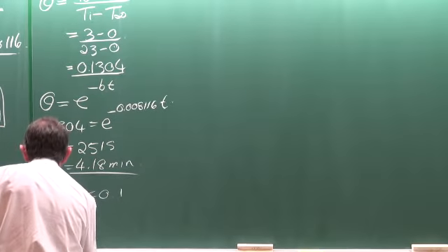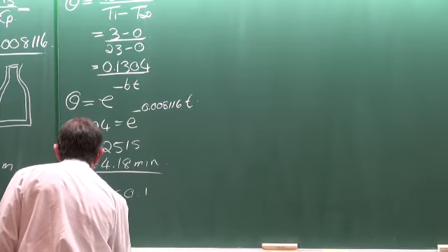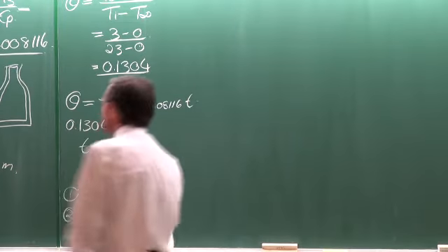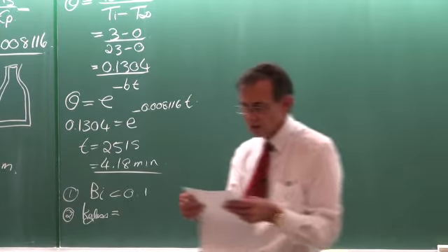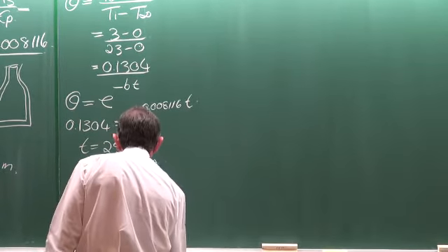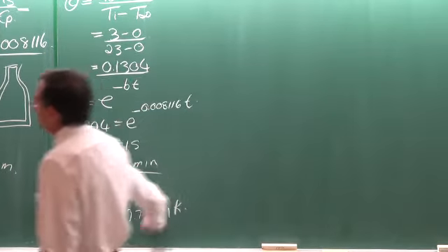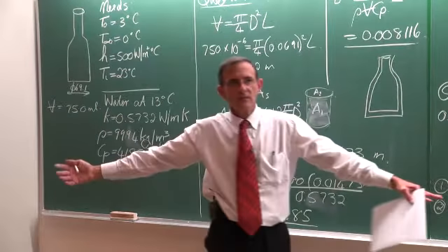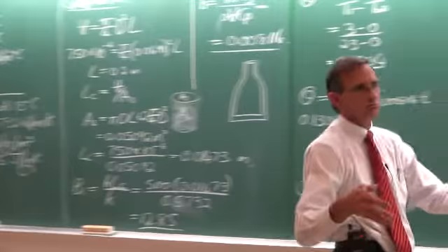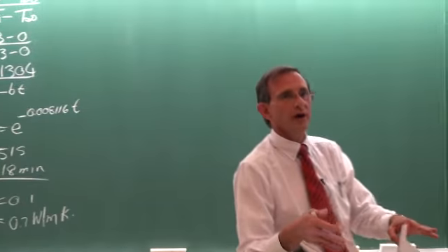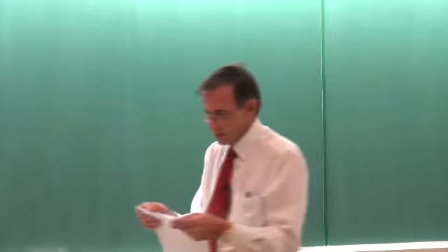But if you go and look at the K of glass, the thermal conductivity of glass, it is approximately 0.7 watts per meter Kelvin. If we look at the thermal conductivity of water, you would see they are about the same. So the glass, or a thicker bottle of wine, is not going to have an influence on this problem. Okay.